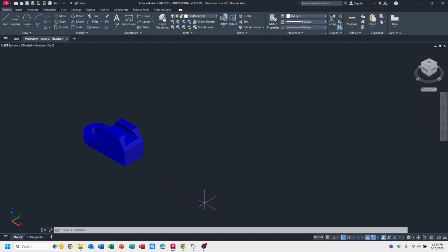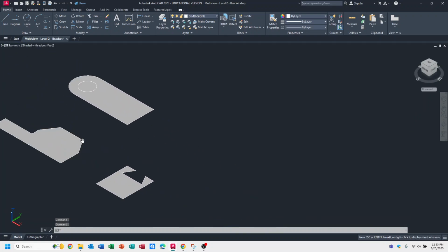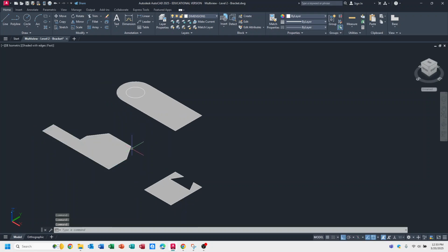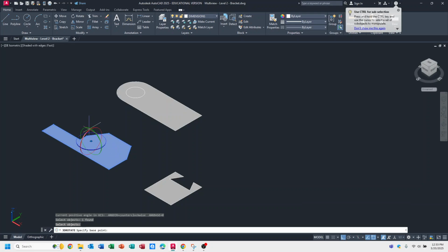And you want to line them up just like that. Okay, so going back to my drawing here, I would need to keep that how that is, but this one I would have to rotate. And if you guys remember the command for that, it's 3DR rotate, enter, select your object and hit enter, and this little gizmo will come up.